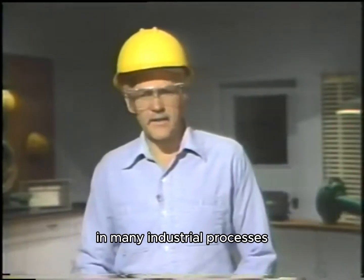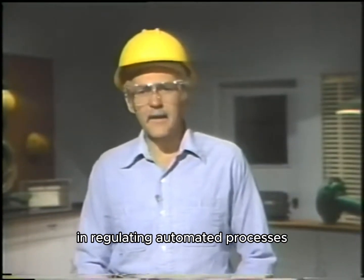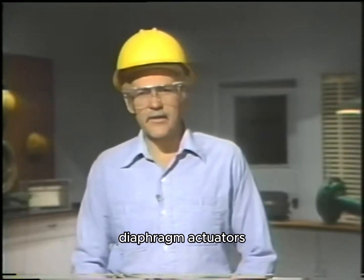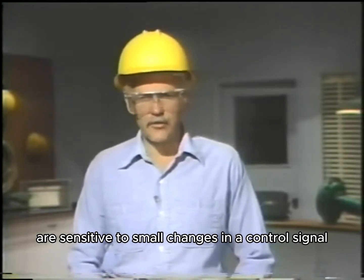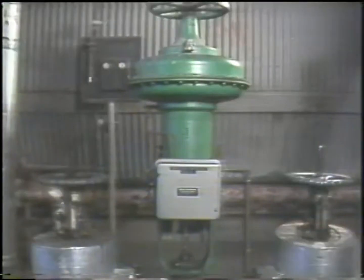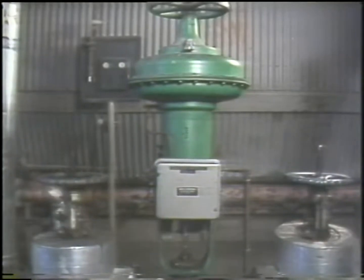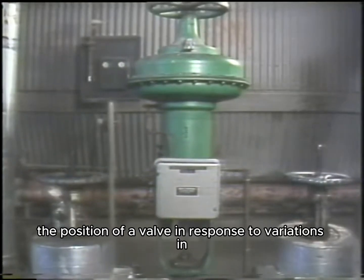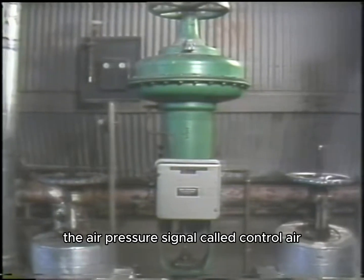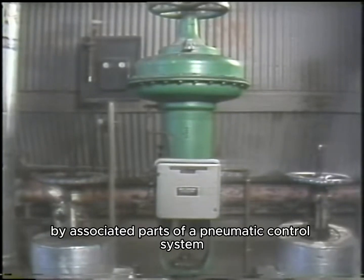In many industrial processes, pneumatic actuators play an important role in regulating automated processes. As we've seen, pneumatic diaphragm actuators are sensitive to small changes in a control signal and are capable of very precise positioning. For example, this actuator is used to operate a valve. It changes the position of a valve in response to variations in air pressure. The air pressure signal, called control air, is developed by associated parts of a pneumatic control system.